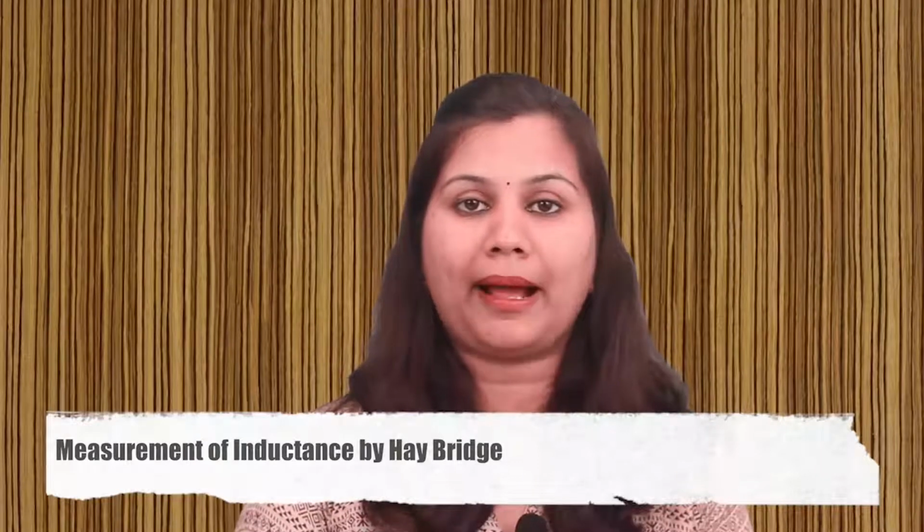Friends, in this video we will study the measurement of self-inductance using the Hay bridge. This bridge is a modification of the Maxwell inductance capacitance bridge, and it measures the self-inductance in terms of the variable standard capacitor. So let us start with our topic.